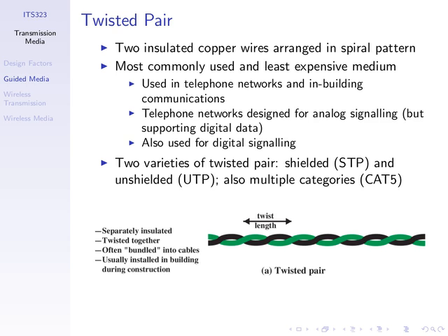If you've got a gigabit Ethernet card, we can send 1,000 megabits per second. To transmit at that speed, it actually uses all 4 pairs. So most computers nowadays have a LAN interface that supports both 100 and 1,000 megabits per second. It depends whether the device you're connecting to supports both. If so, you'll transmit at 1 gigabit per second. And that uses the same cable, but uses all 4 pairs rather than just 2 pairs. When you're using the normal 100 megabits per second, 2 of the pairs are wasted or are not used.